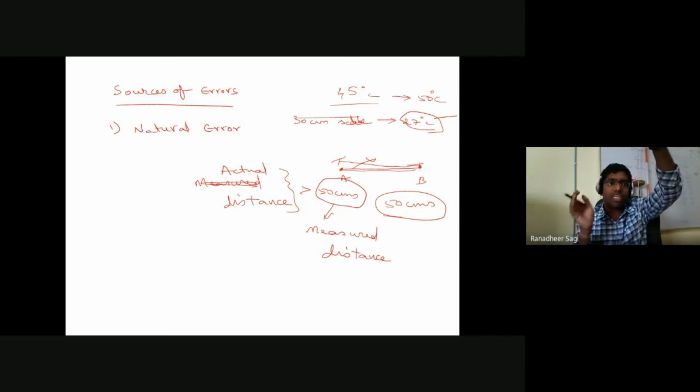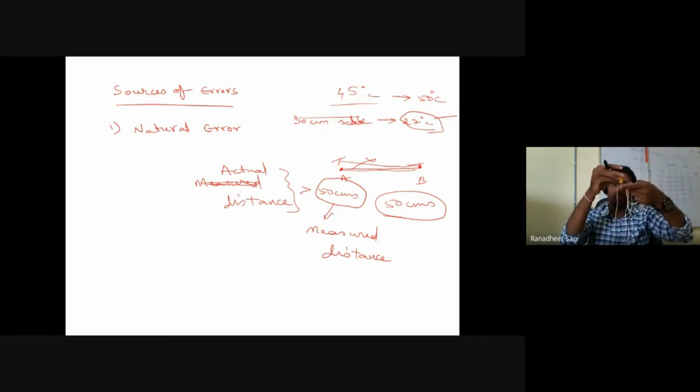Okay, so let's say there is a wind while carrying out the survey. Due to the wind, you are not able to transfer the exact position of your location onto the ground. And as there is a wind, the point of the bob, which was supposed to be indicating where my station is, is not exactly locating the position of that station. Rather, it is getting shifted to some other new point, and it is showing me the station somewhere else.